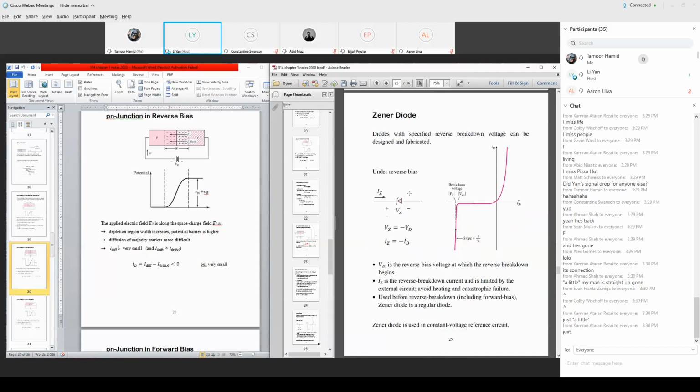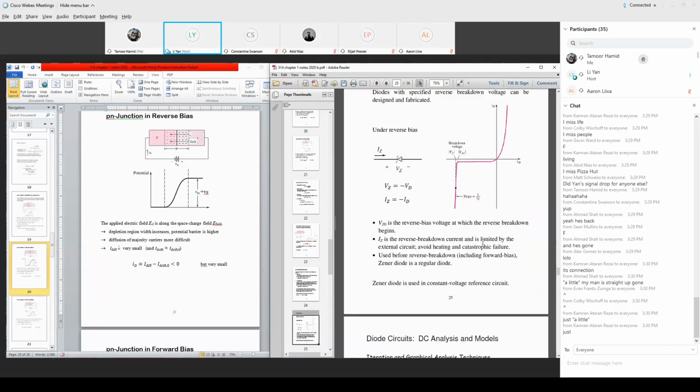And this diagram shows a normal diode, but if you want to use it as a Zener diode, you reverse bias it. Your plus side polarity lines up with this side, and the negative side polarity lines up with the triangle side. And IZ is defined in the opposite direction, so VZ in terms of polarity is really just opposite of VD. The IZ current direction is defined as opposite to ID. Just the opposite way. So IZ is the reverse breakdown current.